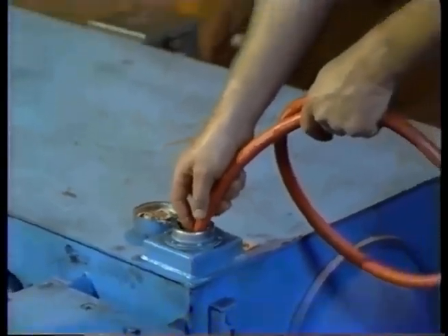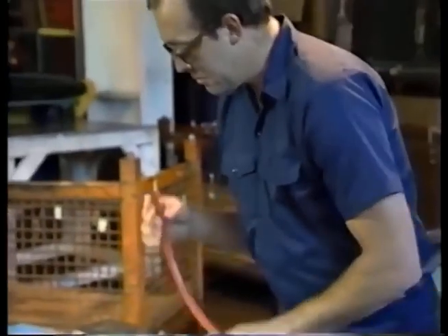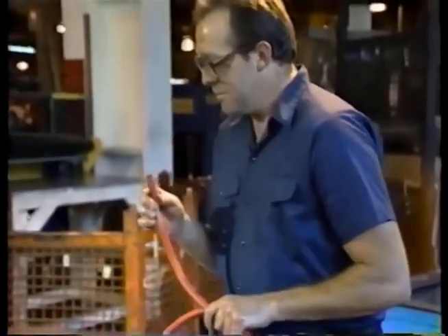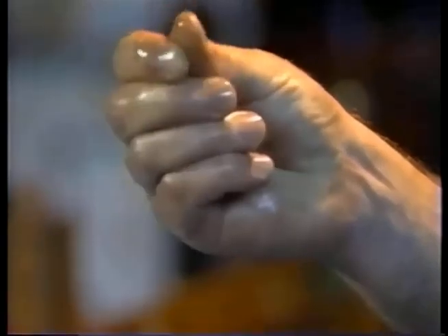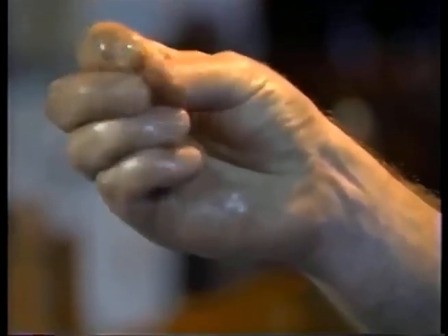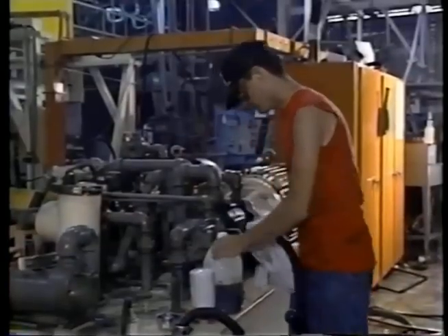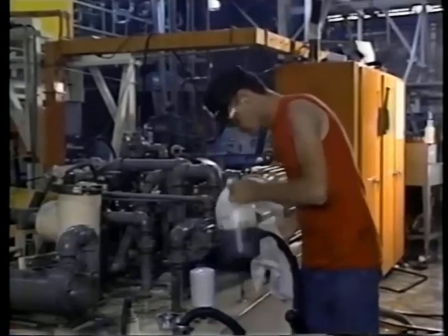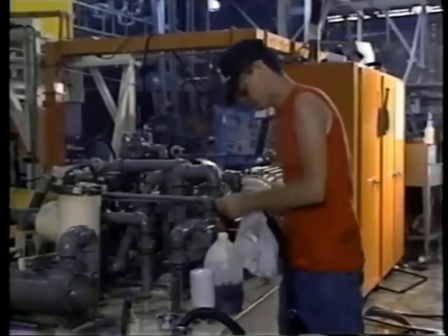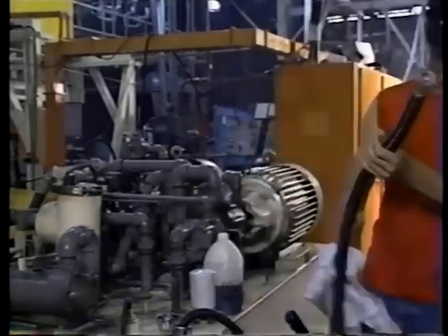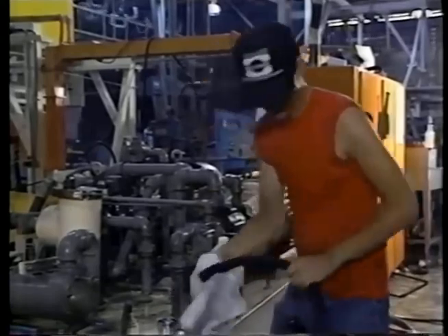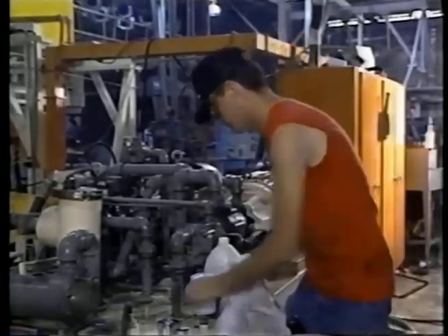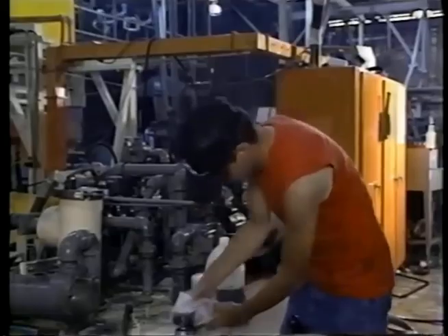Oxidized oil can often be detected by smell. It usually has a burnt odor. Oxidized oil can also be identified by rubbing some between the thumb and forefinger. It won't have the lubricity of new oil. Instead, it will feel more like water. If a fluid sample has either a burnt smell or feels too thin, and if a fluid analysis indicates that the fluid has been oxidized, you will have to drain and flush the system, clean the varnish deposits and sludge from components, and refill the system with fresh fluid.